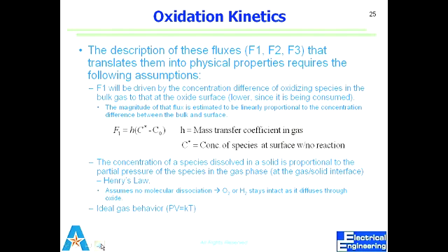Do thin oxides have the same quality otherwise? Yeah. Unless the high voltage results in breakdown, then tunneling starts occurring. So tunneling is the major challenge with thin oxides. Otherwise, they are exactly the same. They're just thin. Except for their thickness, the voltage can break it down easily.